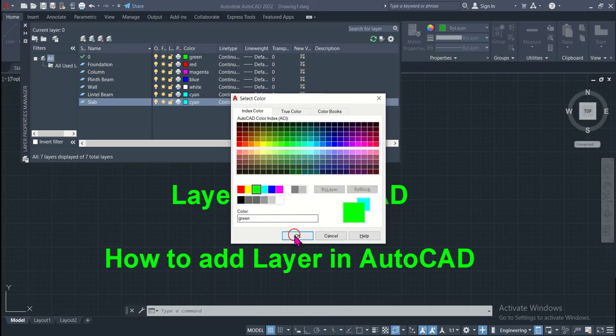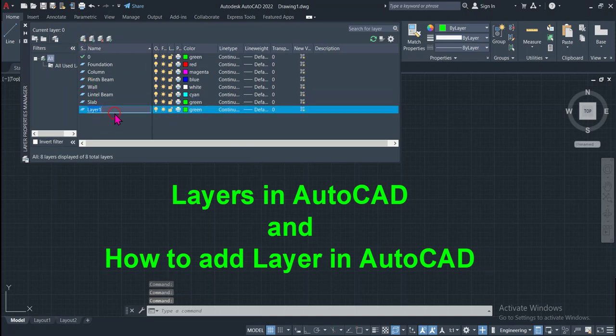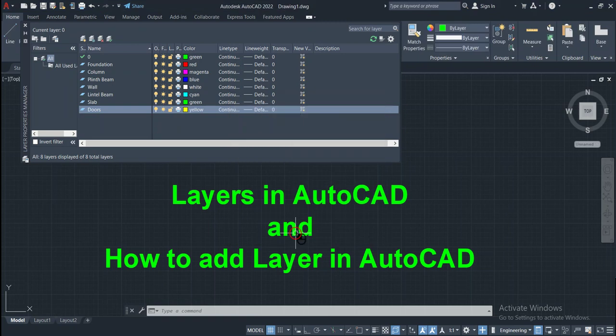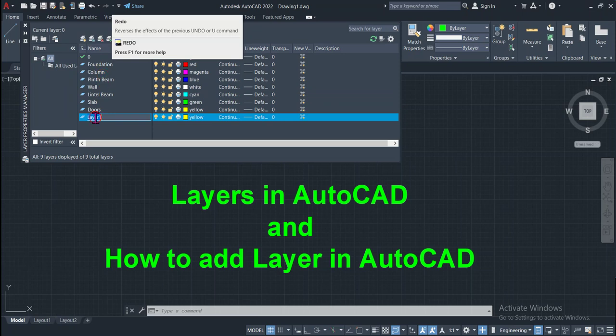We want to assign it a green color, and we can add another layer and name it doors, and we can change the color to this yellow. We can add an unlimited number of layers in the layer category.